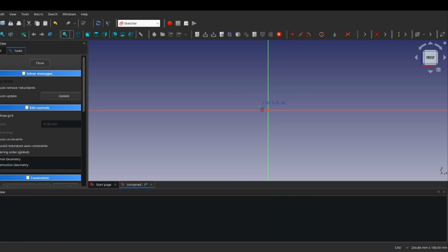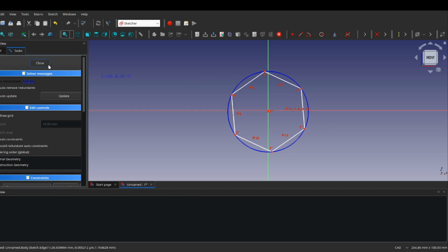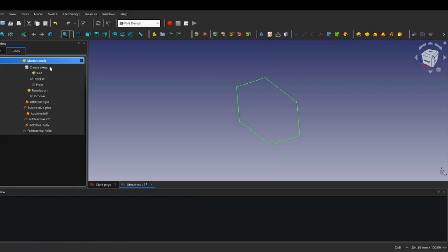And that's another thing with Freecad. With Blender, you just put the shape on. In Freecad, you have to actually make the polygon. I had to make the polygon, rotate it however you want. And then another difference, you've got OK or Close, always Close.